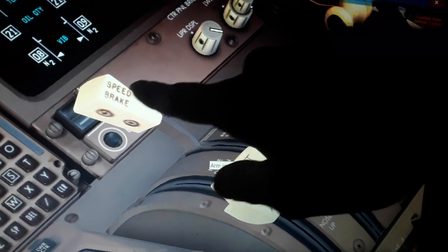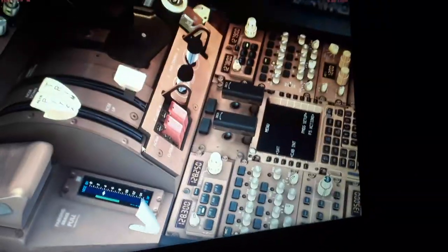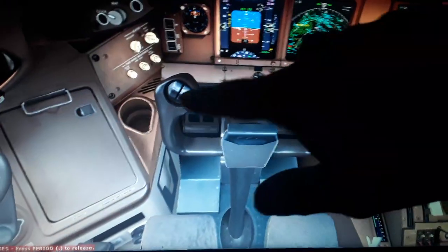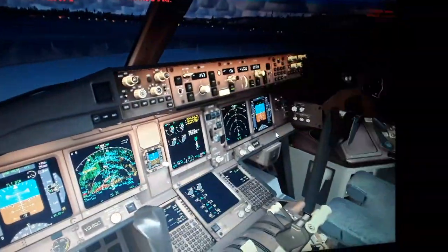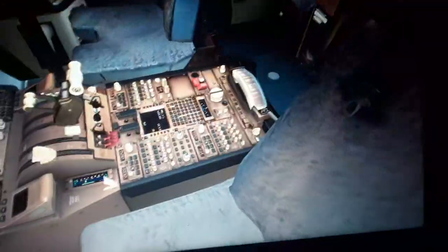We have also the speed brakes, which extend when the engines are idle. Over here you cannot extend like this. So also, if you have a failure of the C or the R of the auto trim, the hydraulic system, you only have the manual trim after. You lose the autopilot and the auto throttle trim order.